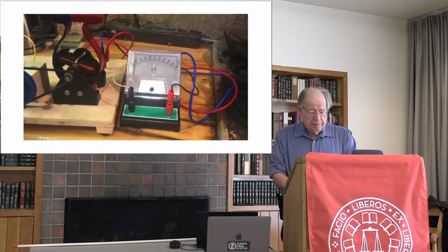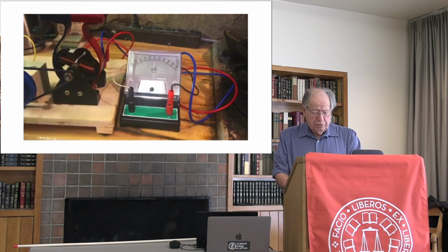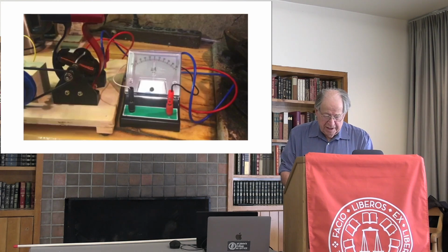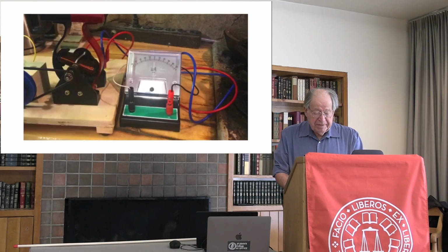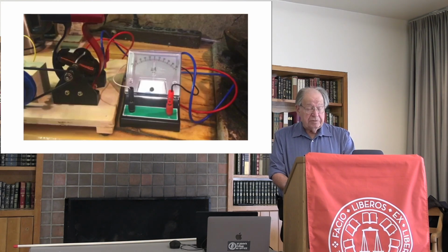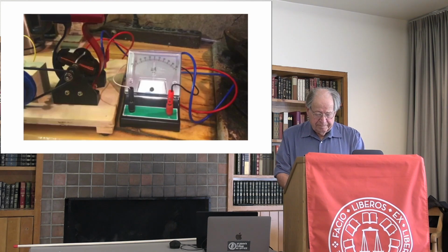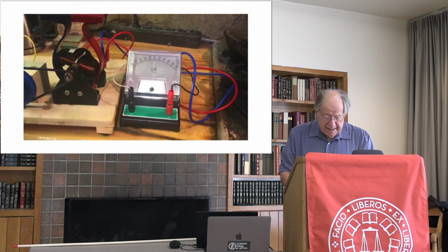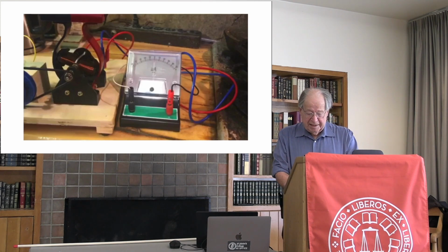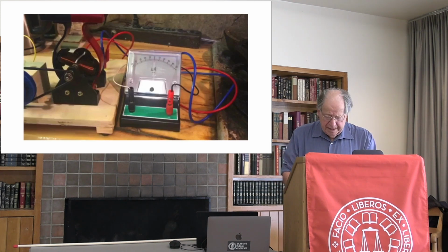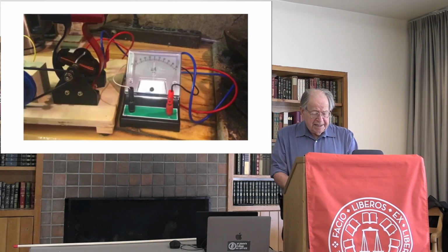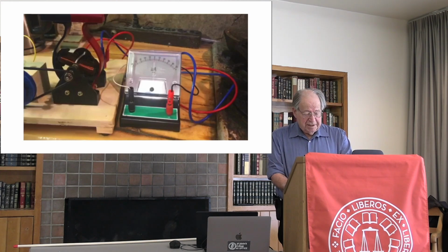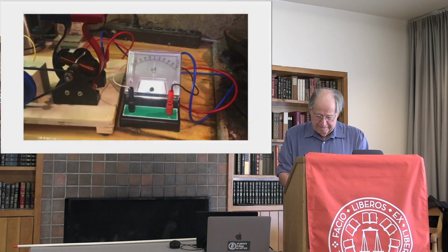Whatever its value, our meter readings will be proportional to the peak values of current or voltage, and it is these peak values we shall be interested in. So remember that even though the meter is steady, the alternating current, or voltage, in the circuit will be continuously oscillating between these positive and negative peaks.